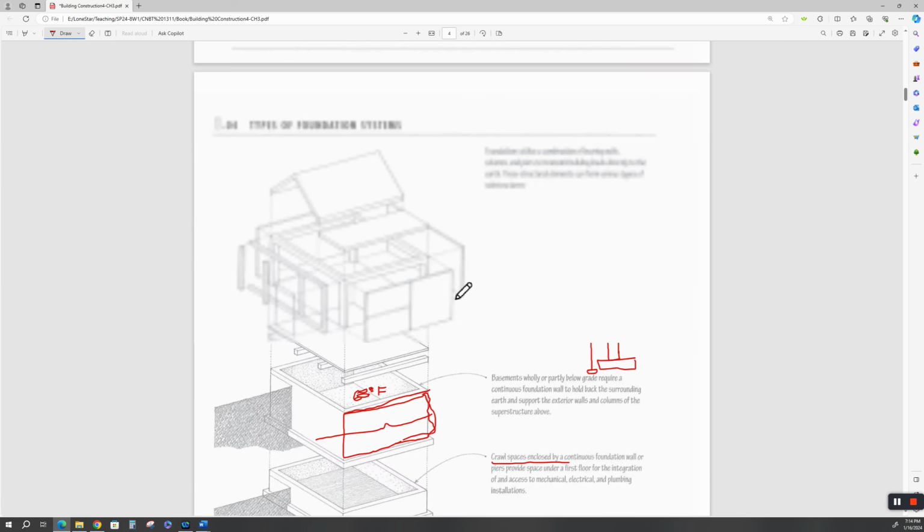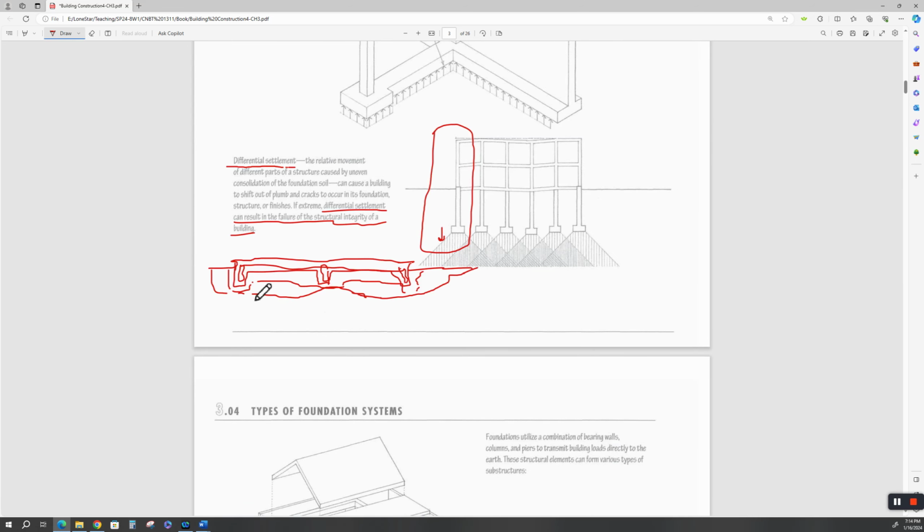All right, so concrete slabs on grade, they're spread out uniformly. Okay, I drew one up here. And if they're done properly and the subgrade is handled properly, then the weight of the structure, the walls and any interior load-bearing walls on the grade beams, uniformly spread the load across the slab.